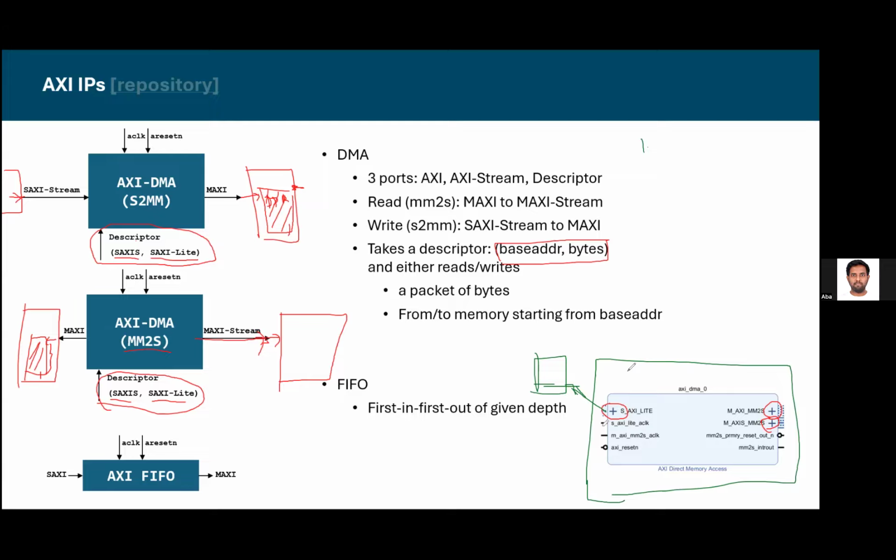And then it is also inconvenient because you have to generate this DMA from Tcl scripts. You can't generate it from Verilog. I don't know if there's a way, but you can't. So you have to write Tcl scripts separately, which I have done before, but then you have to keep those Tcl scripts correct and all of that. It's a bit of a pain to work with this DMA. So instead, we just got the open source one, put it inside, and connect everything in Verilog. That way you have connected all the stuff, and you can control the descriptor also from Verilog. You can give your addresses and let the DMA do the stuff.